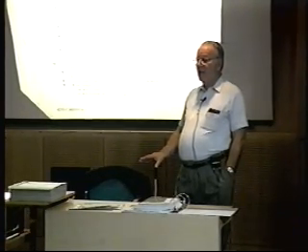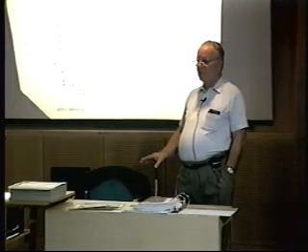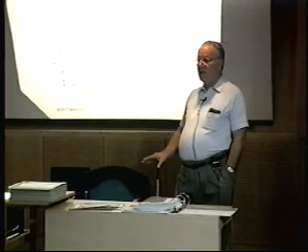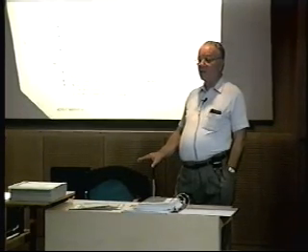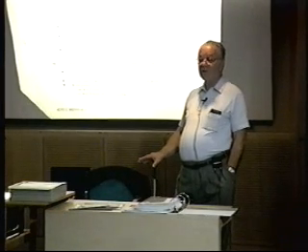We analyzed them all. You can't skip over it, because everything has to make sense. If you analyze the drawdown and the build-up and you get different answers, you've got a problem, because you better get the same answer. If you have different rates and different build-ups, you better get the same answer. And if you can't do that, there's something wrong, either with your analysis or there's a new problem to solve.